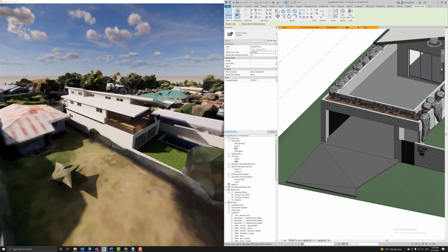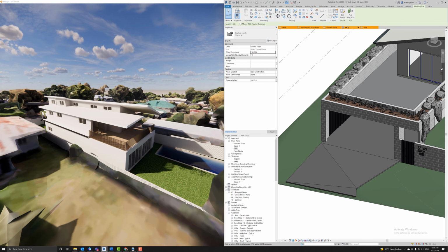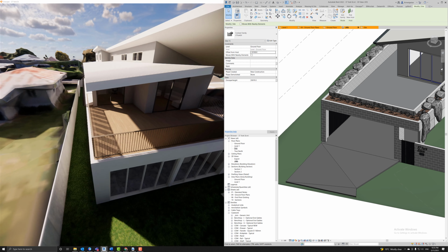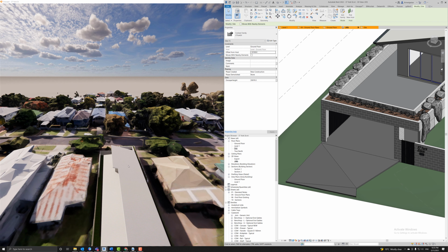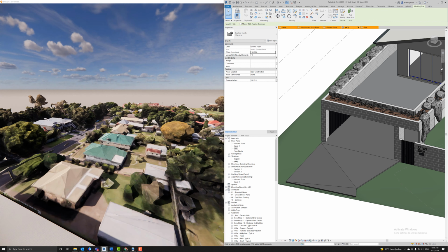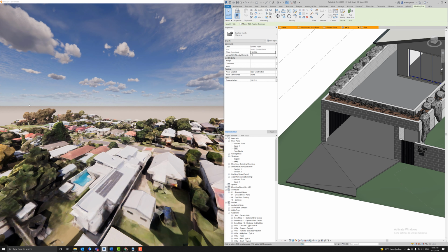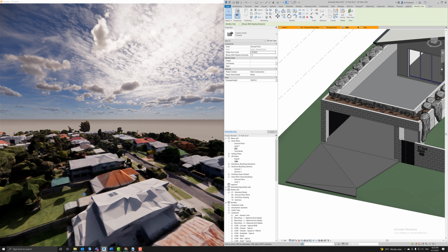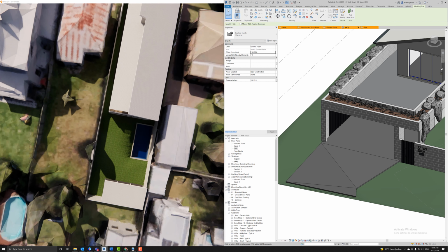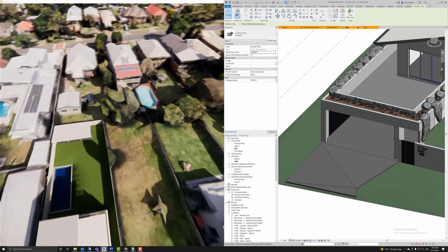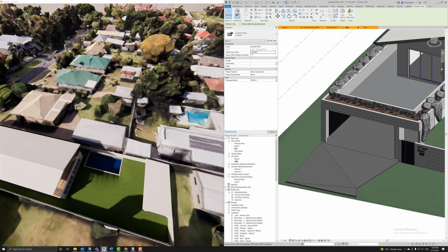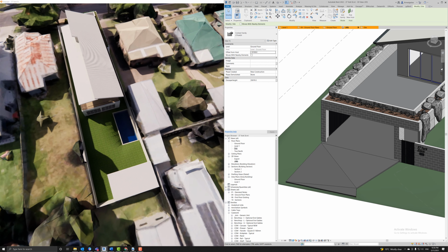The one issue that I've got with this system is that the walk functionality is broken once these are loaded. So if I put it into walk mode, you'll see it just jump up in space. It seems to be jumping up to like the highest point of the asset. Maybe it's the top of this tree, something like that. So it's not treating it the same way it would topo, so I can't actually get it to go down. It just treats it like a big rectangular prism.